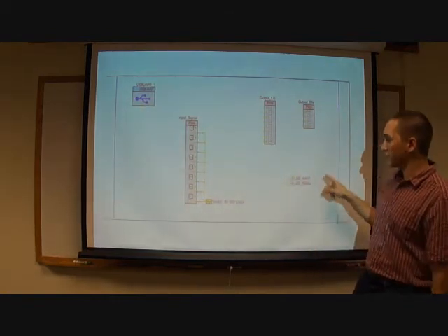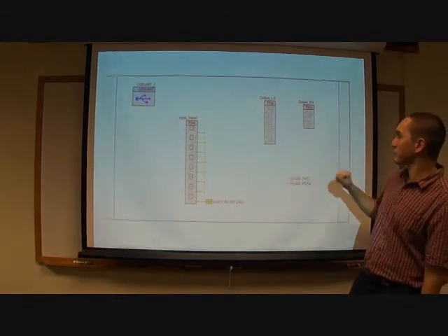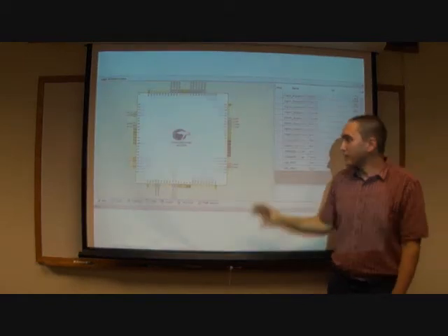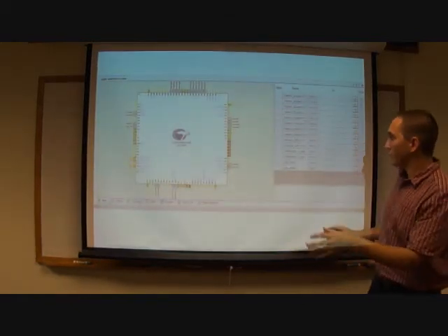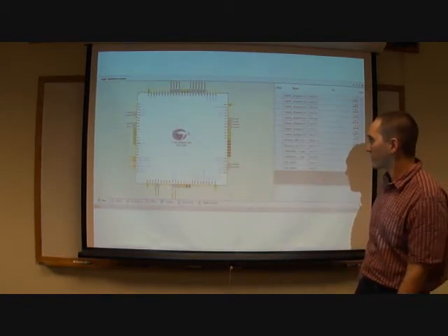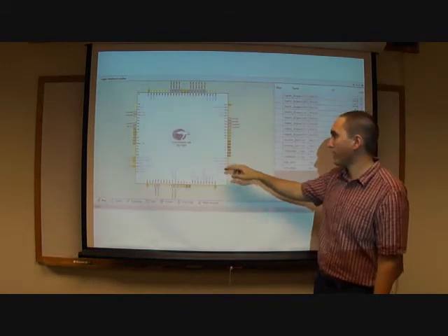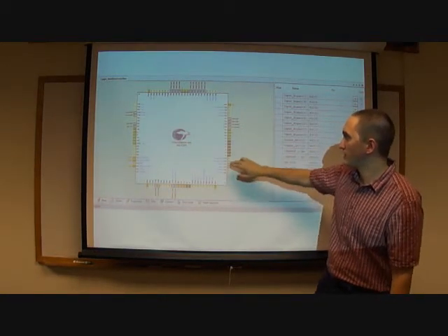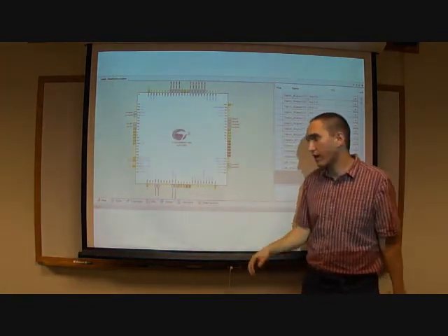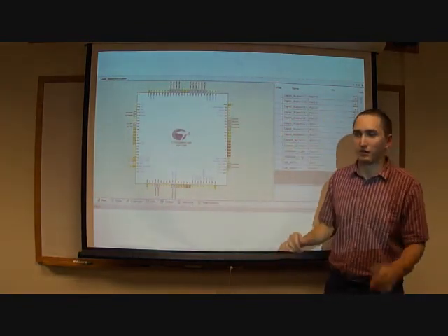And over here we have our LED control output, our output level select, and our output enable. Next slide. This is a screenshot from the design-wide resources, and this helps you label your input and output pins. For example, I've mapped the special input-output pins to these pins, these pins, these pins, and these pins. And those are chosen for their specific inputs on the PSOC5 package.